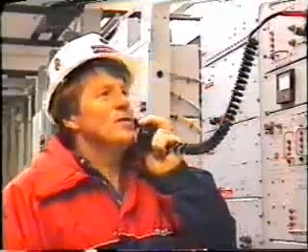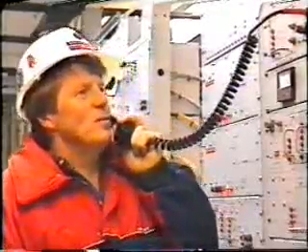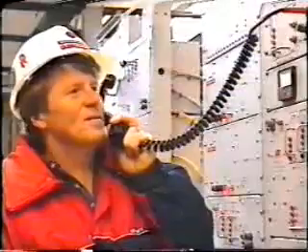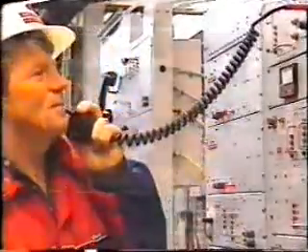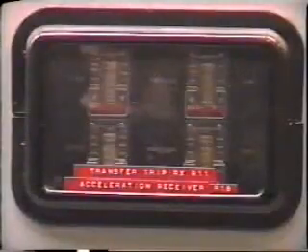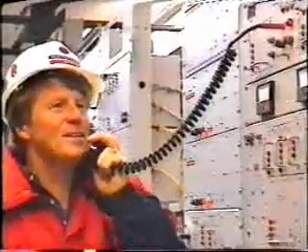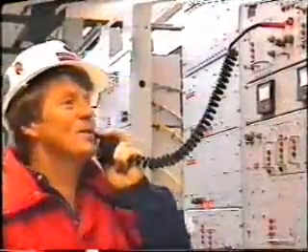Many carriers include facilities for transmitting voice and other audio signals from end to end over the carrier system. The audio signal may be transmitted during the off period of an on-off system, or even across the guard signal on an FSK system. However, the transmission for protective relaying will always have priority and will disconnect the audio transmission when relay operation is triggered.